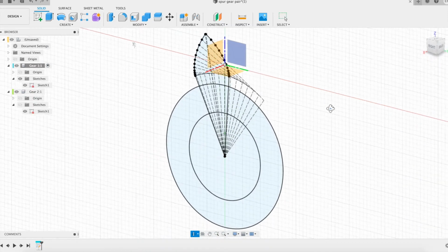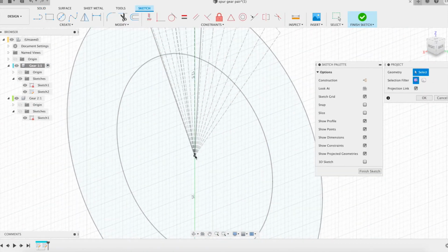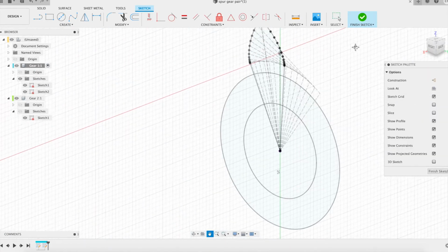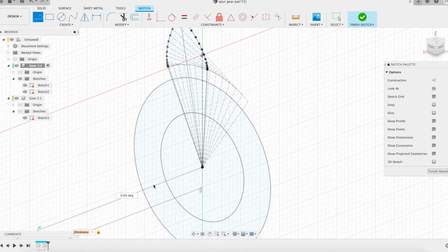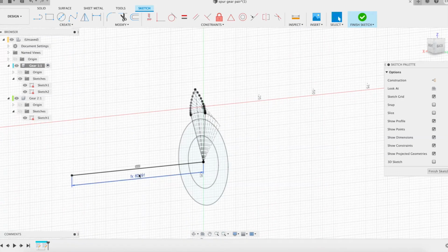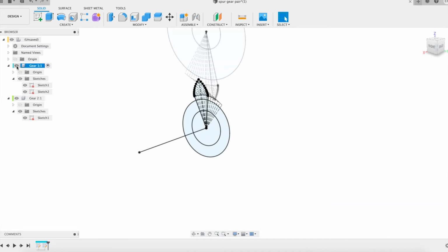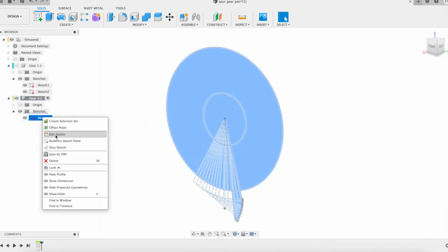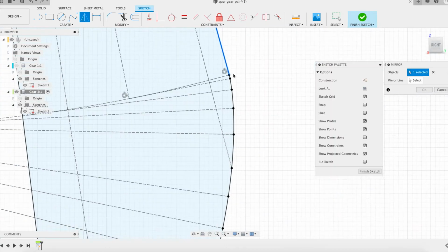I am now creating a second sketch for the pinion. It contains a point obtained by projecting the pinion center point from the first sketch. Then from this point I draw an axis whose length corresponds to the pinion thickness. That's it, this second sketch is complete. It's the turn of the sketches of the gear wheel. I proceed in a similar way to the pinion.